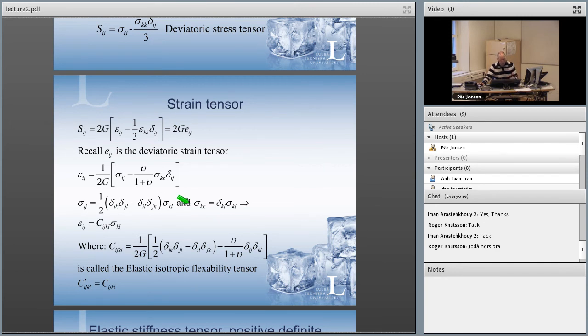You know these equations, from these G and K, bulk modulus and shear modulus, these material properties that you put into the system. Then you use your strain in the system, for example, or the stresses. Usually we go by the strain because you change the loading. Maybe you put on displacement in your model, and then you recalculate this displacement, the strain, and you know the shear modulus, for example. Then you will have your deviatoric stress tensor from this relation.